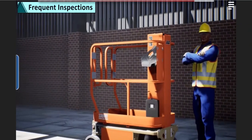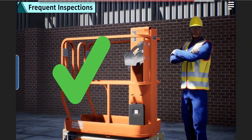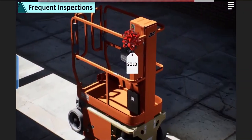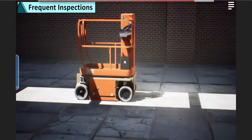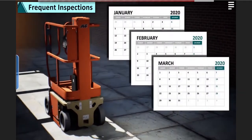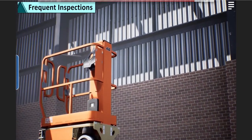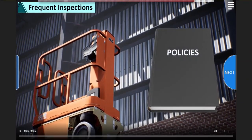Frequent inspections must be performed by a person qualified to inspect that particular make and model of MEWP. Frequent inspections must be performed before a MEWP is placed into service for the first time, before returning a MEWP to service after it was out of service for 3 or more months, and any other time it is called for by the manufacturer or employer policies.